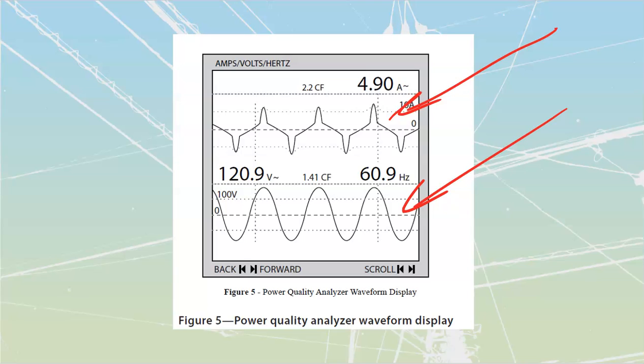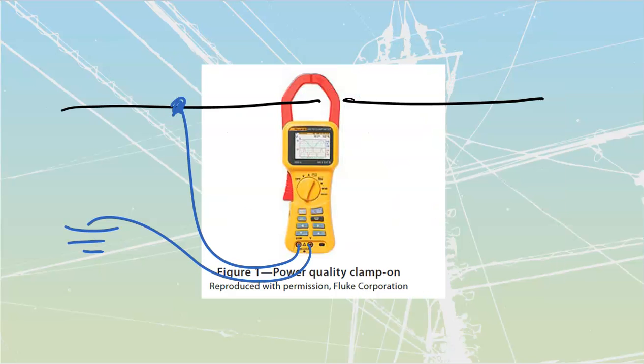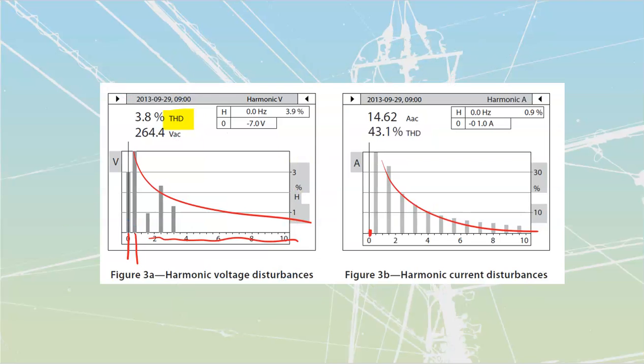Once you have taken your metering, placed the metering on, and figured out what you've got for distortion and where you have harmonics, but specifically the types of harmonics that you have and the frequency they're going to be operating at, you're then going to be able to start to apply some of your corrective actions. Corrective action is going to start on the installation itself with the physical sizing of the installation.